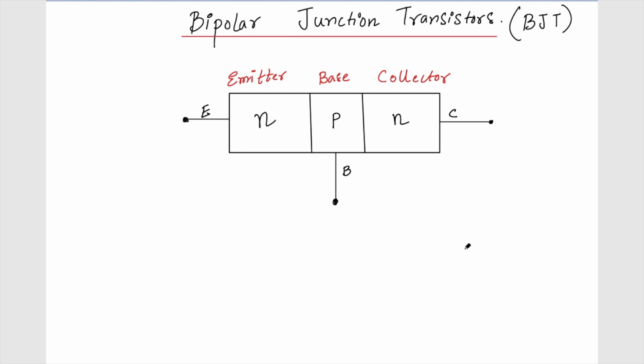Secondly, although this may look symmetric, with the emitter and the collector looking alike, it's not so. The doping concentration of the emitter will be much higher compared to the collector as well as the base. This also we will see eventually.